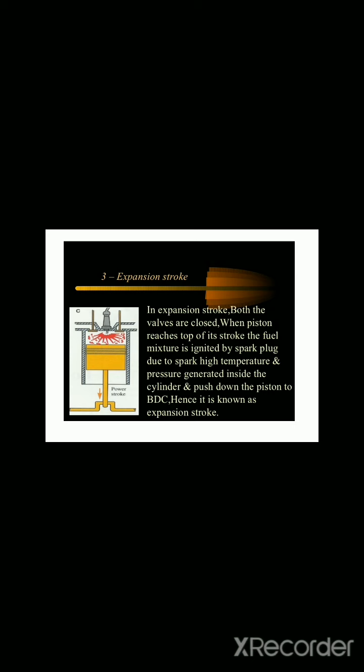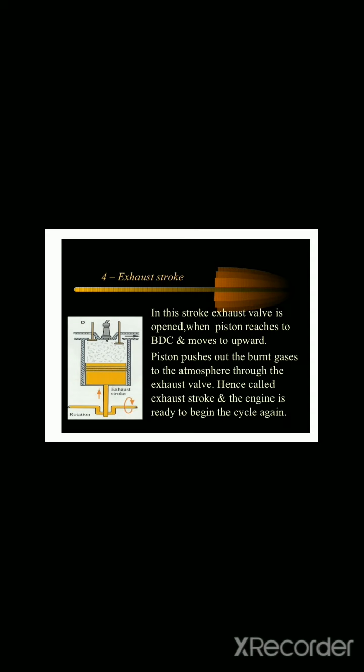In the expansion stroke, both the valves are closed. When the piston reaches the top of its stroke, the fuel mixture is ignited by the spark plug. Due to the spark, high temperature and pressure are generated inside the cylinder and push the piston down to BDC. Hence it is called expansion stroke.